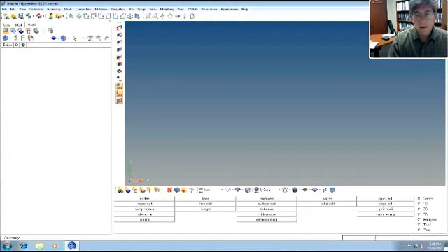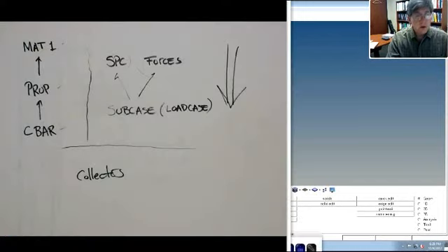You've got things down here, and they're usually reflected by pull-down menus up here. This is sort of the older way of doing it. This is the newer way of doing it. You can use these things to dynamically rotate and pan around. Okay? And the interesting thing is this menu bar on the left, I'll be referring to this a lot. Under model, if you click the model tab, this will be the tree that organizes our finite element model. Okay. So let's go back and define material cards. All right?